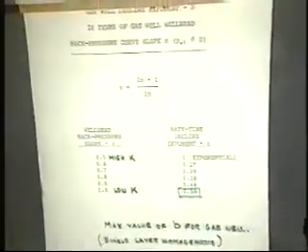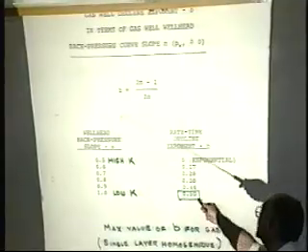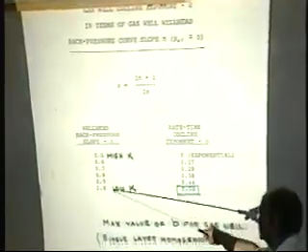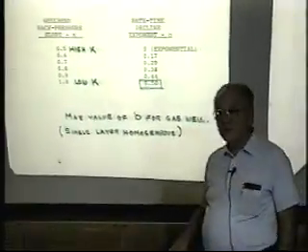By the definition of B, in terms of the slope of the back pressure equation, B is equal to (2n minus 1) over 2n. So for these slopes of the back pressure equation, these should be the decline exponents I should anticipate.